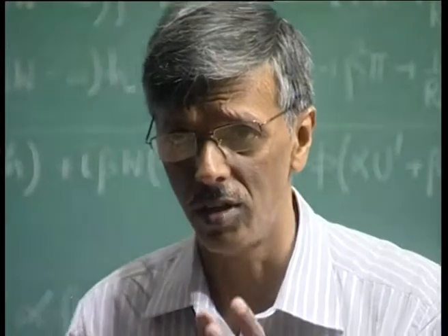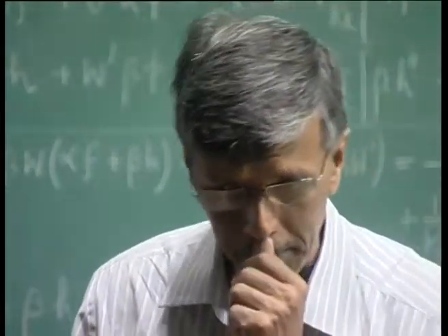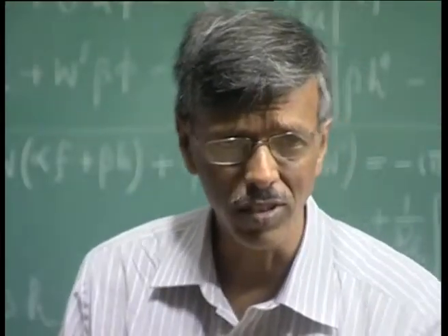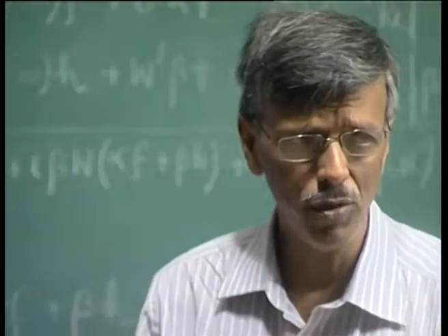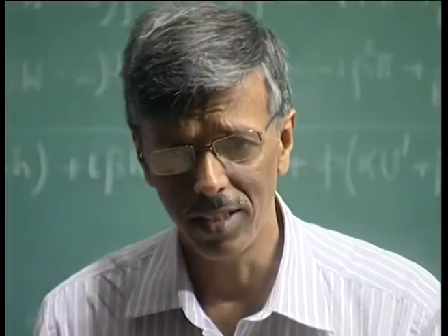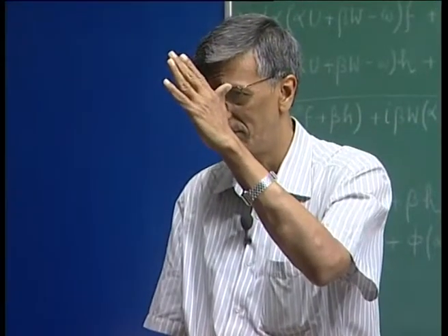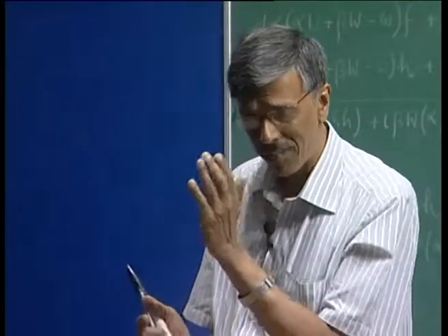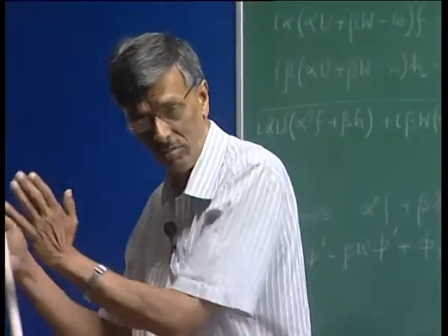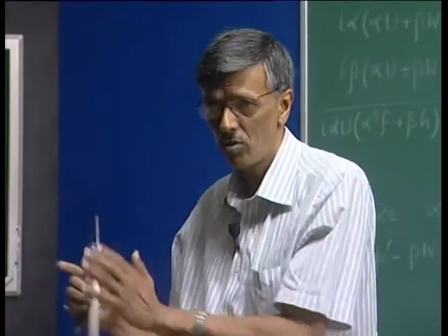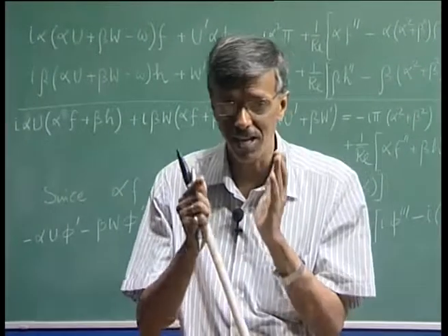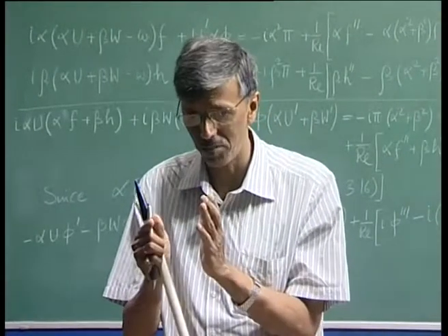You have seen those shed vortices, they do move. But if you look at the near wake point, the disturbance at a given point grows in time. And after a certain formation zone, this convection starts. So, if you are in the near wake, things are happening in time, not in space.